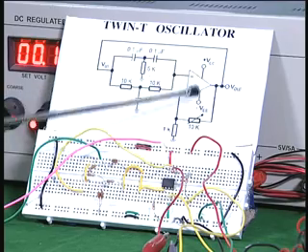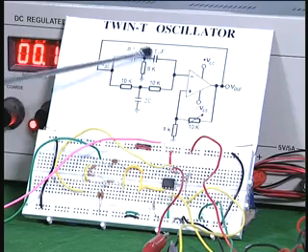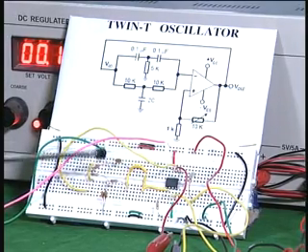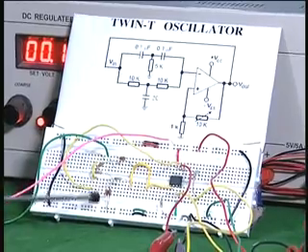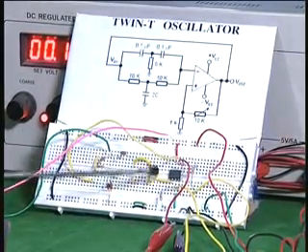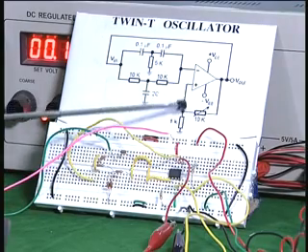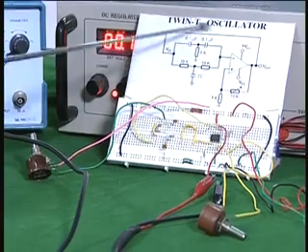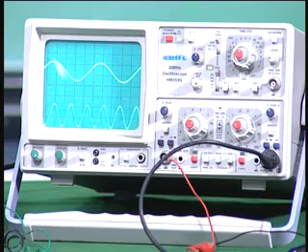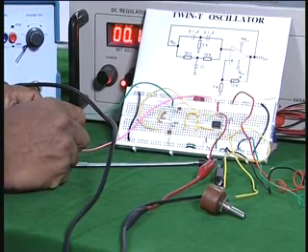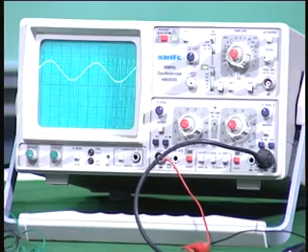Here I have the circuit of the twin T network. You can see the 1 T here, 1 T here. The corresponding circuit is shown with the 2 resistors and 1 capacitor, and the 2 resistors and 1 capacitor here. So, this is a twin T network, and you have the operational amplifier, and one of the resistors here is made as a variable resistor for adjusting the gain, and you observe in the oscilloscope that sine wave generated due to the twin T network. If I vary the potentiometer, you would find I will be able to get the oscillations.